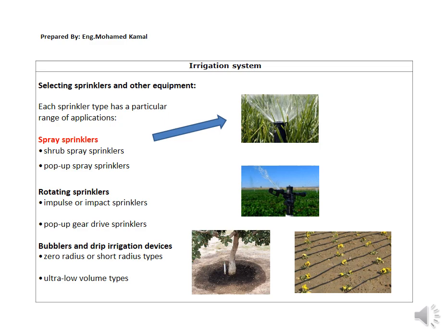A spray sprinkler is a sprinkler which you will already notice throughout the lawn area, and it is mainly utilized for inaccessible lawn areas, as no human or pedestrian will walk through this lawn. While the pop-up sprinkler is commonly hidden under the ground and comes up when it is in the irrigation position. So in this case, it is very reliable and effective for lawns that have pedestrian or walkway areas.